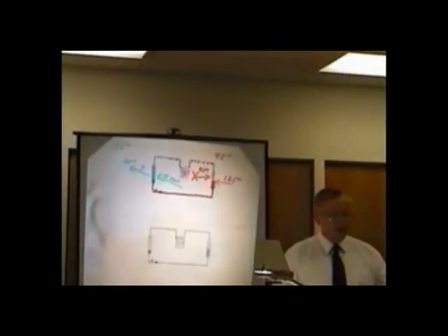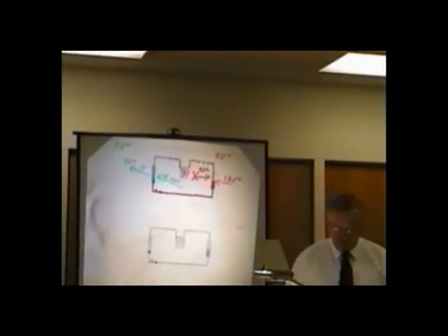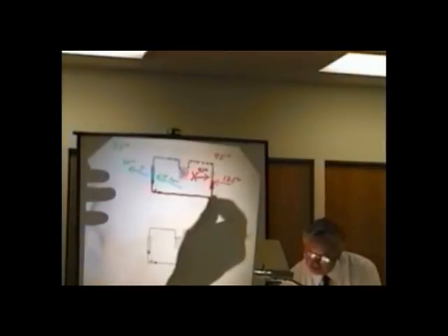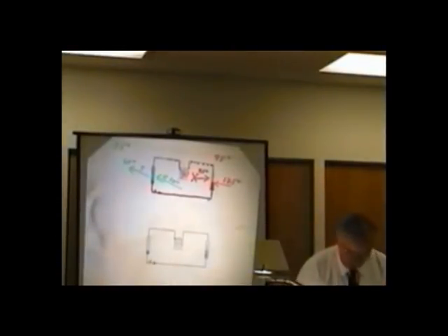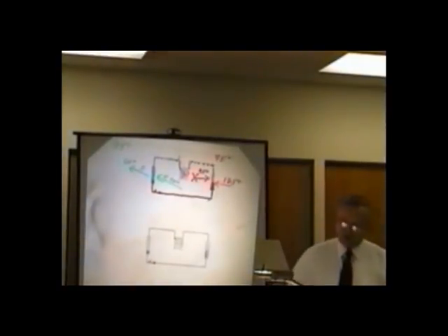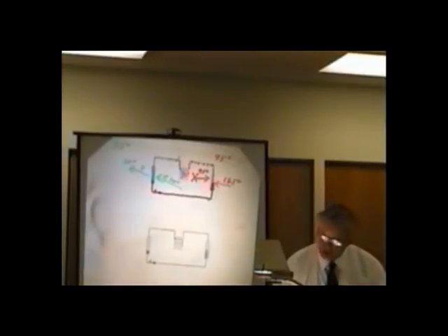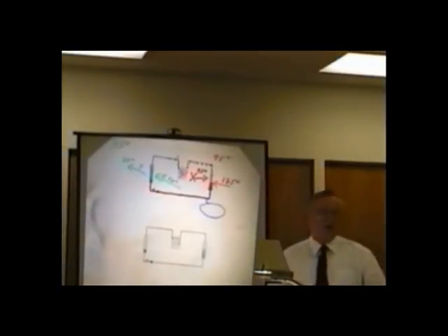We don't know that, except we have a method for us to be able to tell in seconds what temperature that is. Remember that every unit has got a service valve, a high-side service valve at the bottom of the condenser, and a low-side service valve just before the compressor on the suction line. So we have a high-side service valve, ladies and gentlemen, we can take and put a pressure gauge on there.